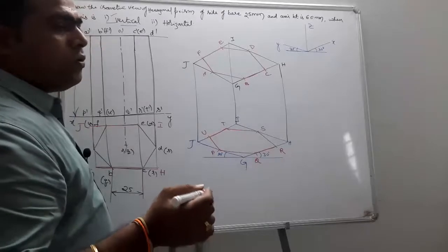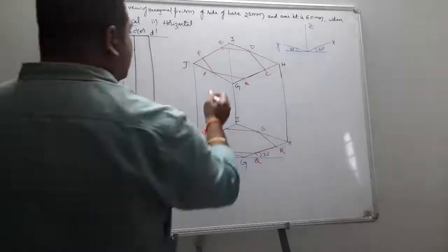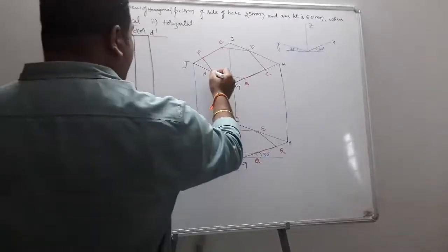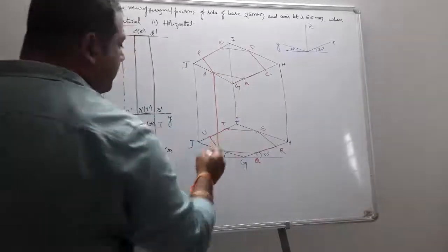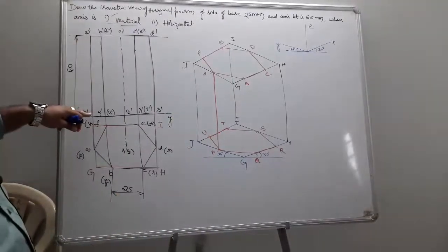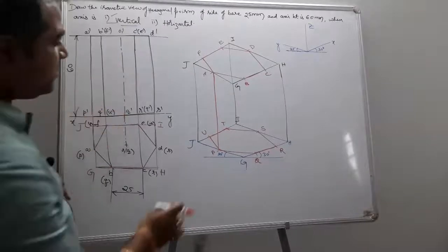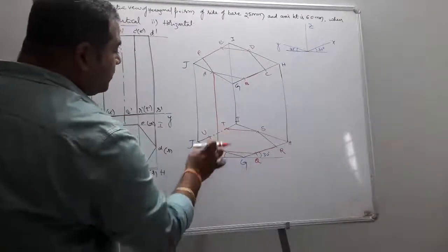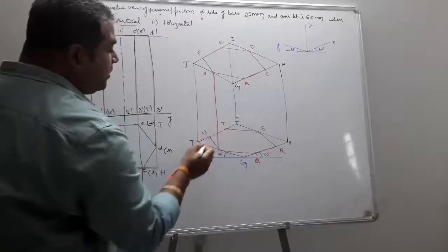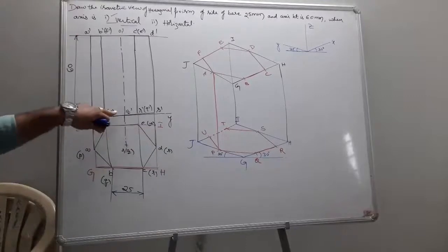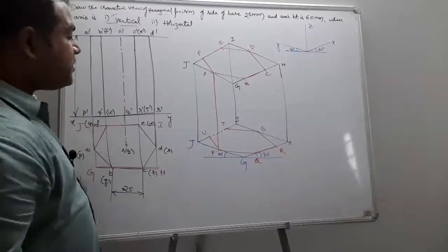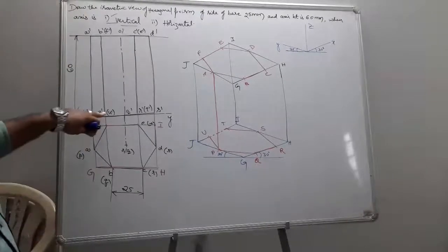We just know no two solid lines can cross each other. So let us see what is going to happen when I draw P with A. If I join P with A, while I am seeing from the front, PA is visible. But UT is going to be invisible, so this is going to be dotted. Why? Because TU is going to be dotted in front of you. Similarly, the lines which are passing from the farthest, that is UT, are going to be dotted.